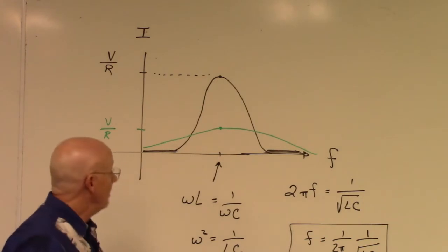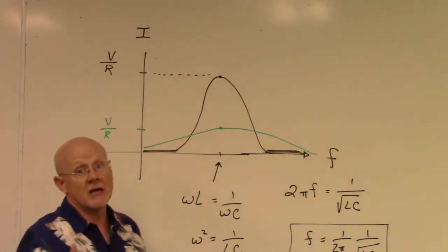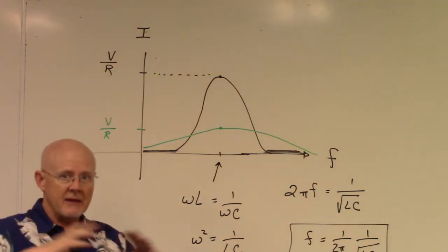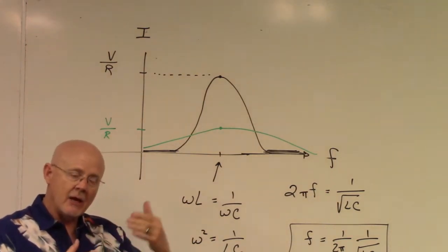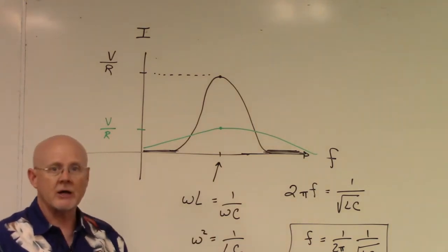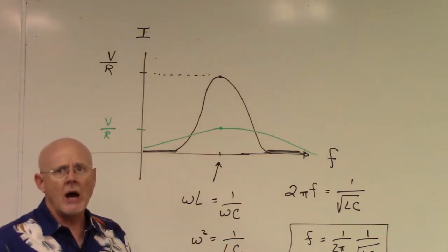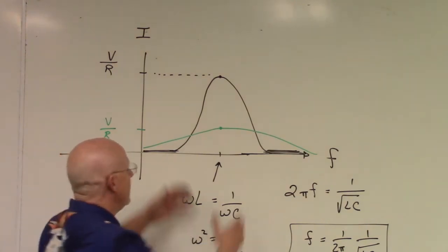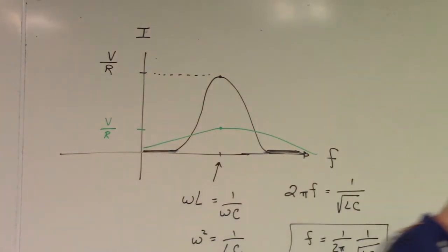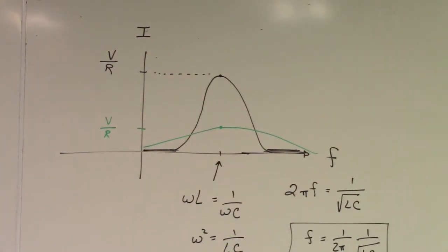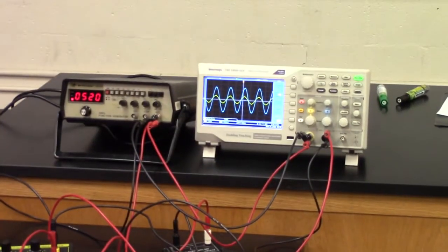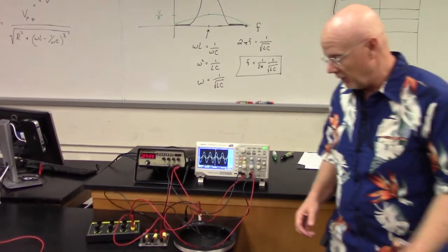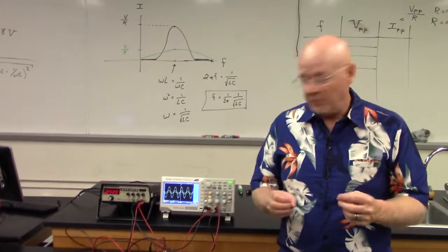Okay? So if you were face to face with me, this is what I'd say. Find the resonant frequency first. And once you find that, then make your measurements at about 10 hertz from each direction. And do that for a while. Once you get, as you'll see, about 100 hertz each way, it flattens out and we can go quickly. Actually, I'll probably go in steps of 10 for maybe 5 in each direction, and then I'll go a little more, like steps of 20, and then I'll finally just go steps of 100. So we'll have a good pattern here.